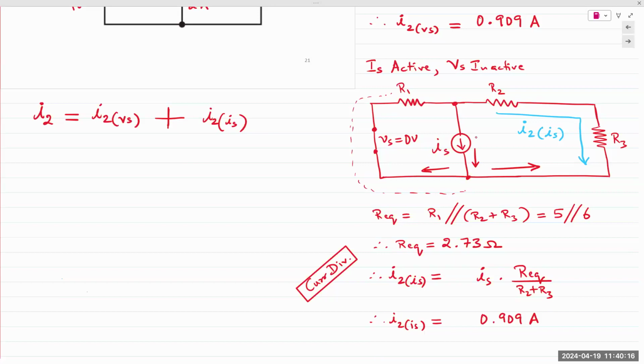Arrow is going from left to right. If the arrow is going from left to right, left end is positive, right end, the arrowhead, is negative. That is how you're measuring the current. That's all it means. It doesn't mean anything else. Again, if a voltage polarity or a current direction is indicated in a problem statement, you are connecting a meter according to the indicated polarity or current direction, what are you measuring? That's all it is asking.